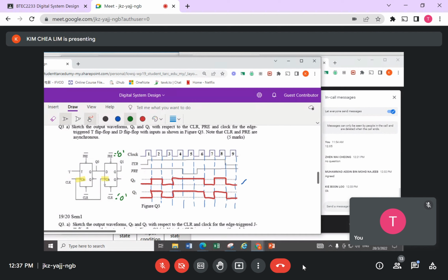This one here should be rising edge, isn't it? Because I normally set questions, I won't set it as an edge like that, because our students will argue. To prevent this thing from happening, okay? So normally I don't do it this way. All right, so this clock here should be rising edge, okay? Rising edge. So things will happen here. I checked, okay, I didn't check the clock just now. So take away this tick here. All right, so anyway, we label first, rising edge.